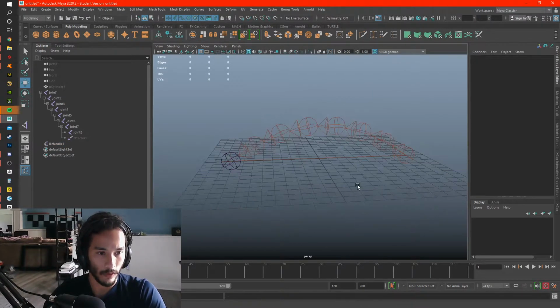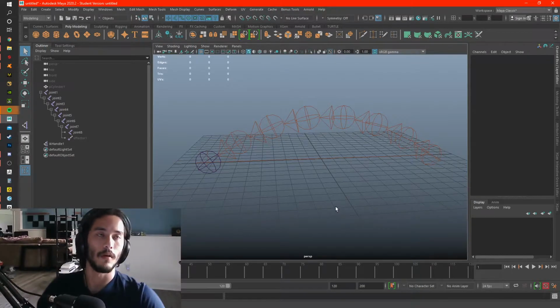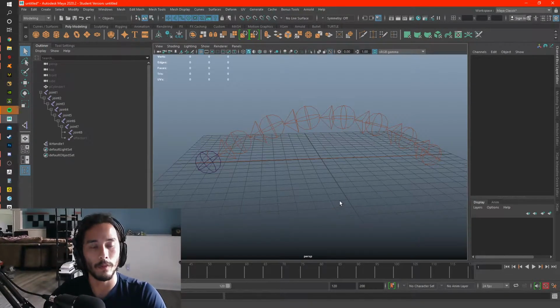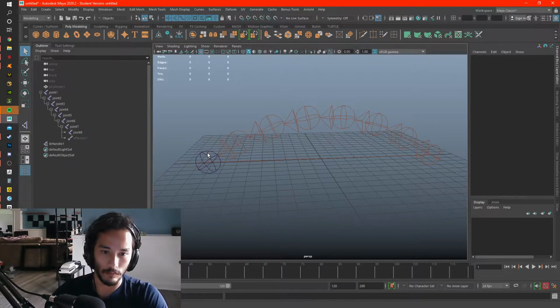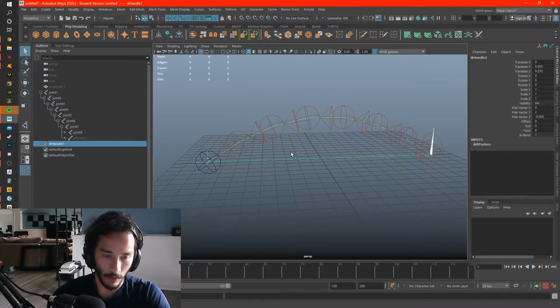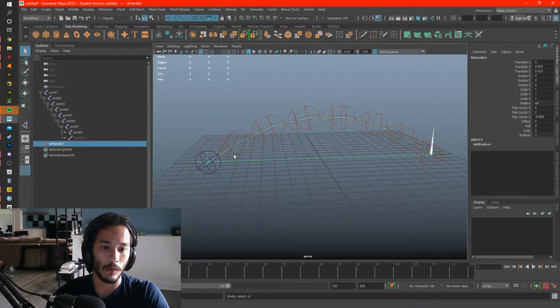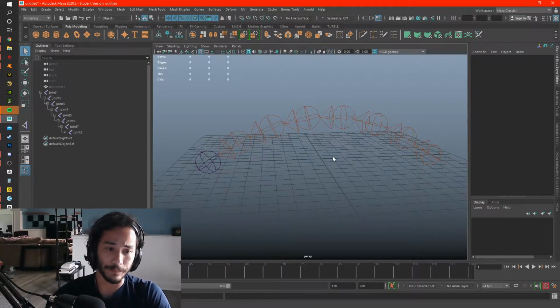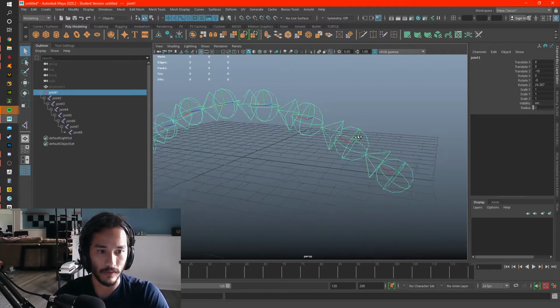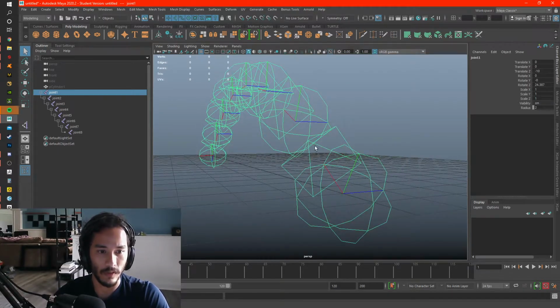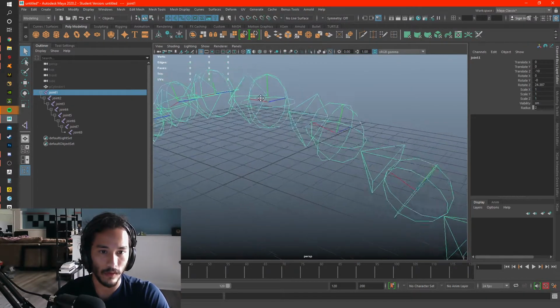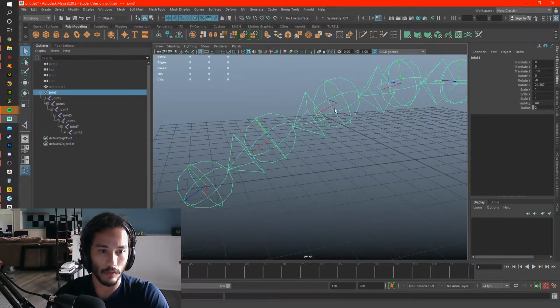So what I was going to go into real quick is, before you put IKs on any bone chain, you have to do something called orienting your joints. What that is, when you click on the joints, you can see what axis the joints are, what is pointing down the chain.